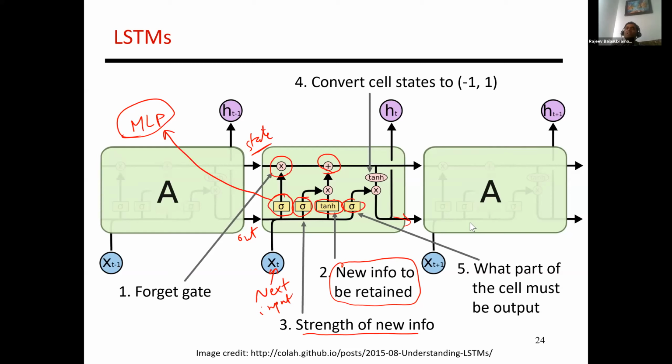And so in response to dark silicon, chip makers can put in an assortment of accelerators, and that's compatible with how workloads actually run, where they use some kernels some of the time and a different kernel the rest of the time. So a suite of accelerators, I think, is a good solution to the dark silicon problem, and deep networks just happen to be one of those accelerators.